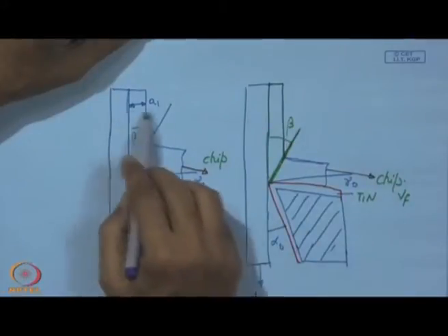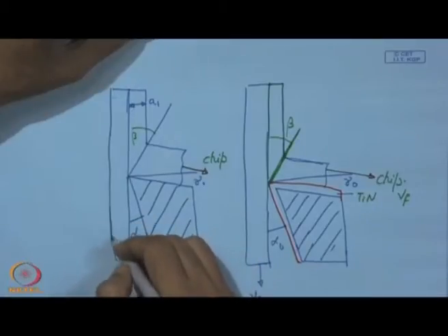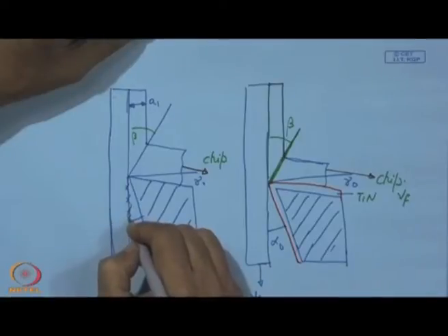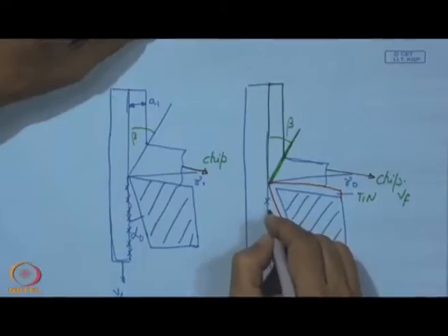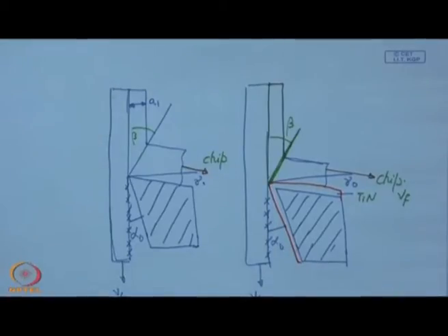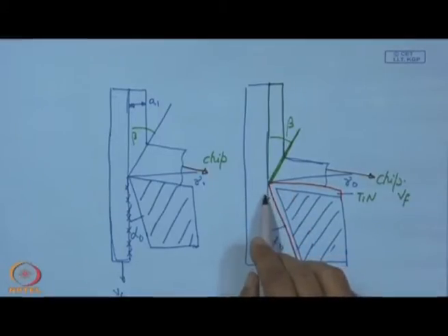That means, this thickness is removed. So, out of this portion is removed. So, this surface is actually the machined surface, that means machined to dimension, cut to dimension. So, the flank is actually facing this machined surface. So, here we find at least two zones where there is severe rubbing: on the face and on this side which is facing this machined surface.